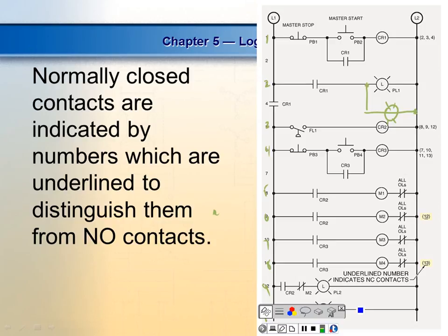So they don't number on the airplanes. On the airplanes or the military airplanes, they actually put the wire number every 6 inches. And in an airplane, the planes I worked in, all the wires were white. They were white jackets. But they put the wire number every 6 inches.